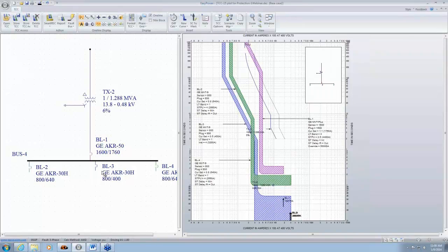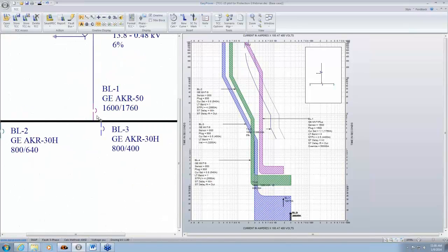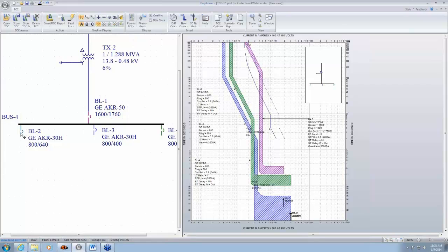Now the question is, I've got feeder breakers here crisscrossing. The curves are crisscrossing. Do I need to fix that? Since they're on the same level, you do not need to coordinate feeder breakers with each other. You only do between different levels. So I would say main is one level, all these circuit breakers are second level. You have to look only between upstream and downstream circuit breakers or fuses. So these can be left as they are, it's fine.